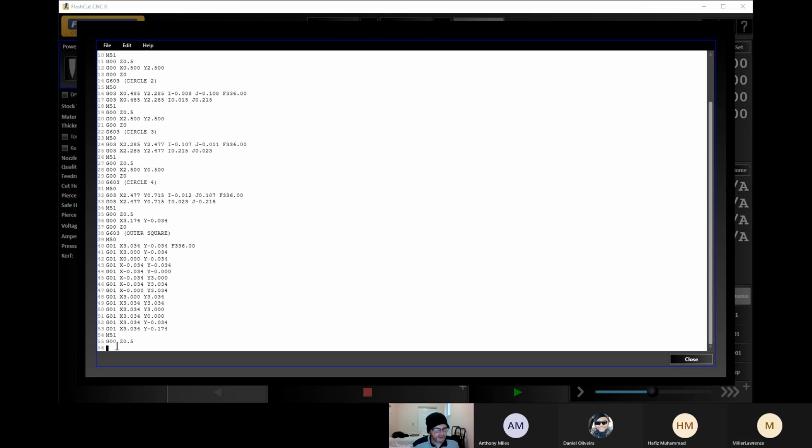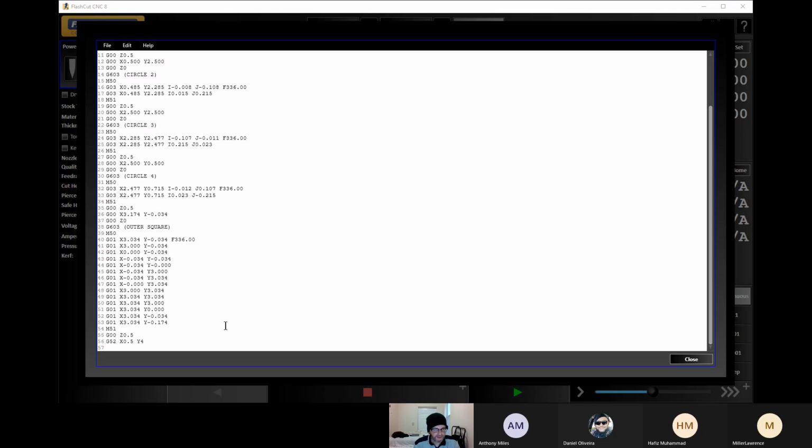We're going to go down to line 56. We're going to put in another G52. We're going to say X 0.5, Y 4. We're going to hit enter. We're going to lower the torch back down to operating height.